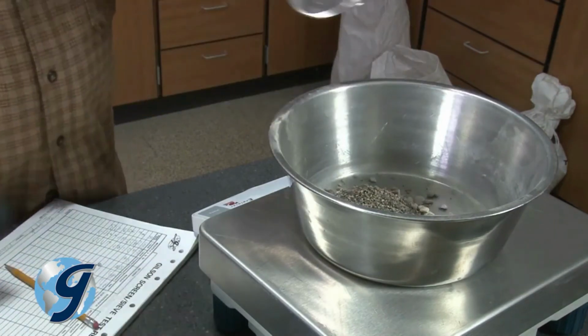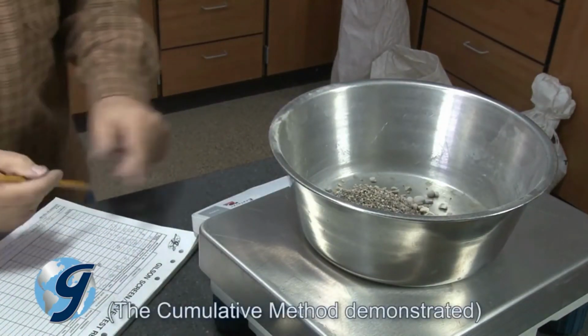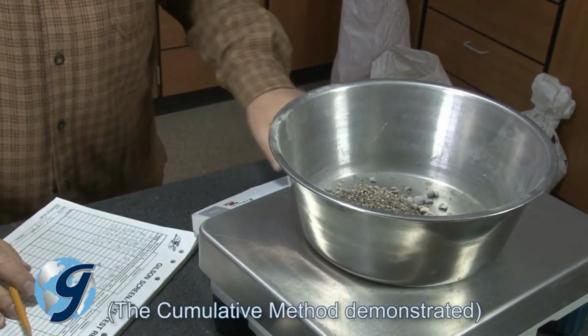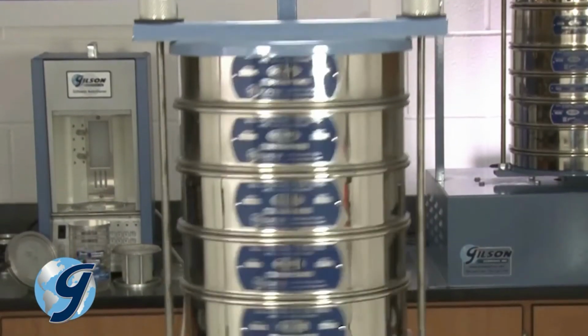The total mass of the sieved sample should match closely with the original mass of the test sample before sieving. If the amount differs by more than 0.3% based on the original dry sample mass, then the results should not be used and the test should be repeated.